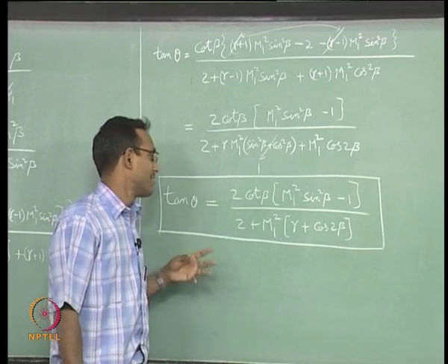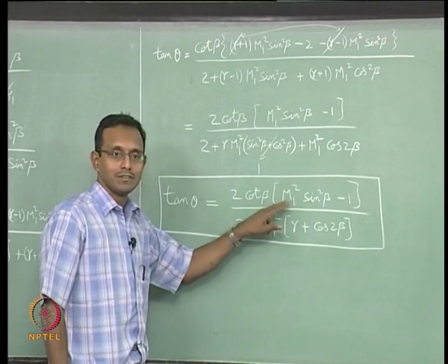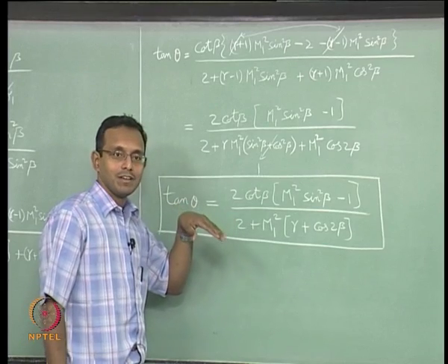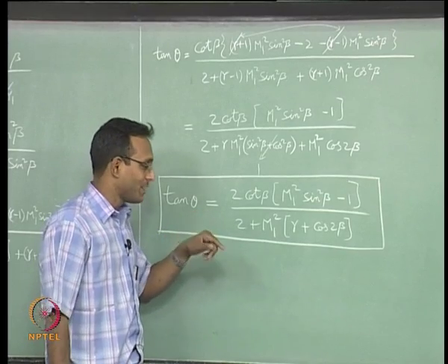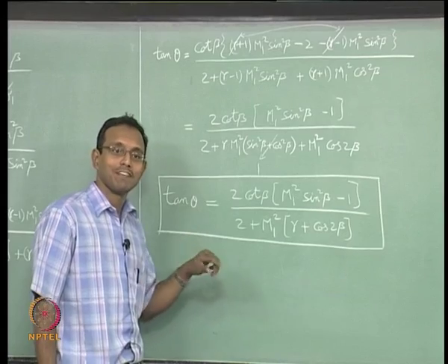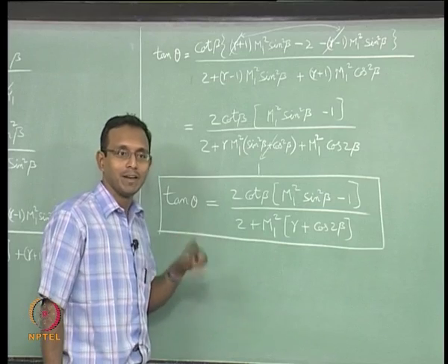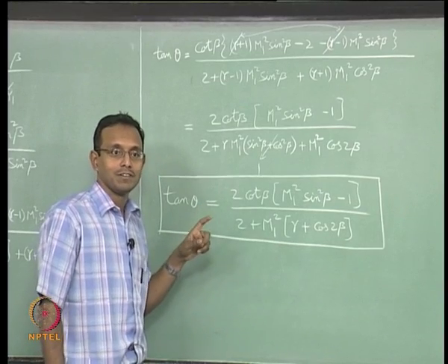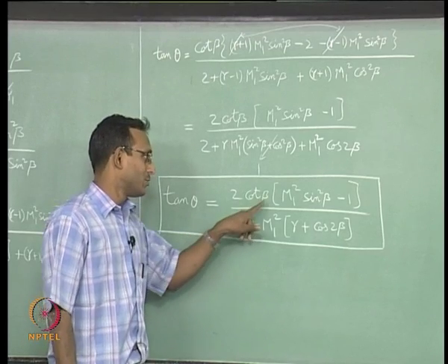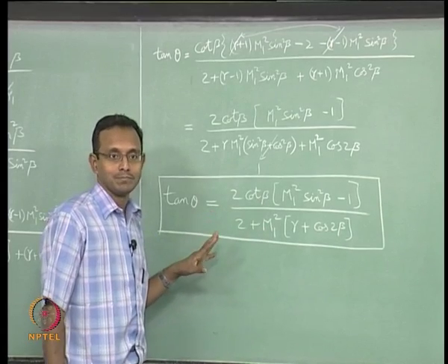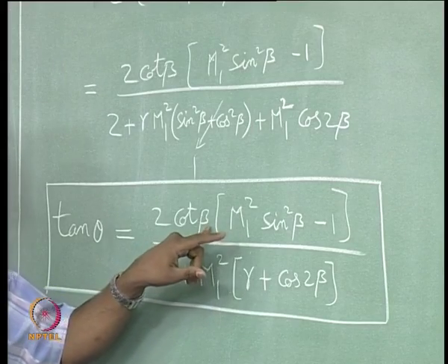We will have a case where I will be given the theta, I will be knowing the Mach number, that is I know my body shape, I know that the body is tilted to the flow with some angle. So now I have to find what is the shock angle there, because only after I find beta I can go and calculate any property, right. I need to know m1 sin beta, that is a normal Mach number. Once I know that, I can go to normal shock tables to find out properties across the shock. So I need to know the beta, that is what will typically be the problem when we are solving in engineering. So given a theta and m1, I need to find a beta.